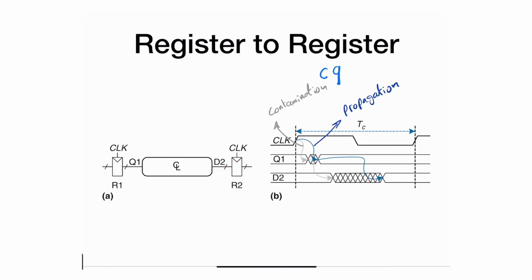As it turns out, this timing analysis I'm about to do will, if this is maintained, result in the maximum frequency, and you're going to see with an equation the maximum frequency, or the shortest, minimum clock period, appear in that. Just one note before we get started into the setup time and the hold time: